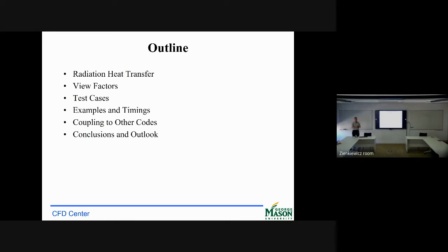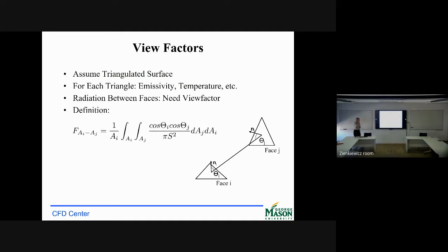So the most important algorithmic part here that is expensive is obtaining the view factors between one surface and another. Okay, so I just want to cover this a little bit. So we assume that we have a triangulated surface, say a complete city, take Barcelona, so think 1 million up to 10 million triangles. And now we want to get the view factors between these triangles as quickly as possible.